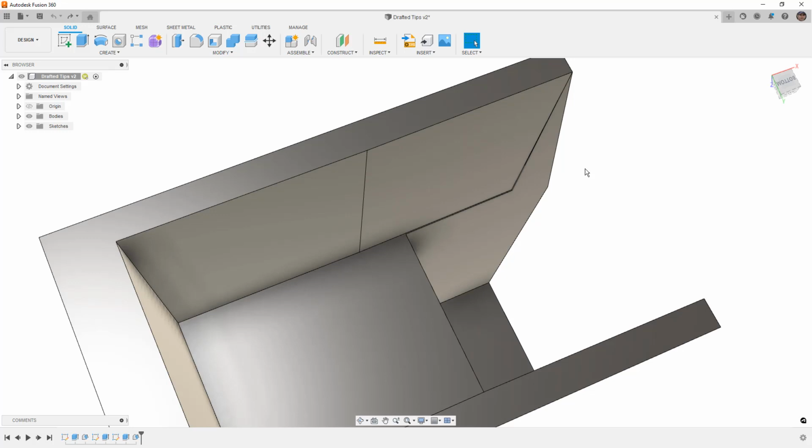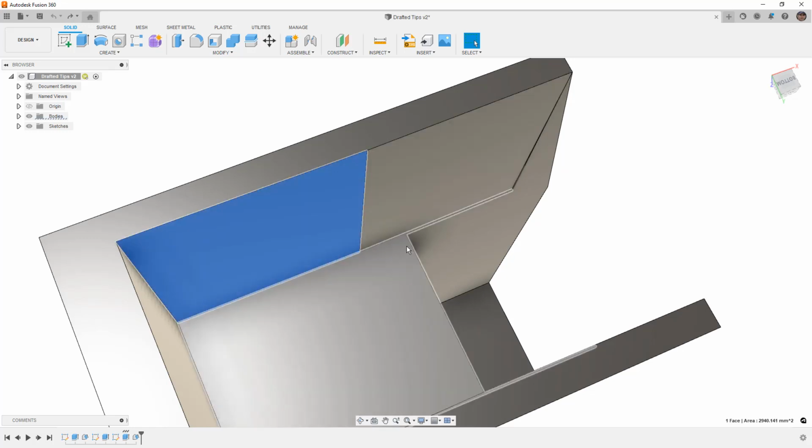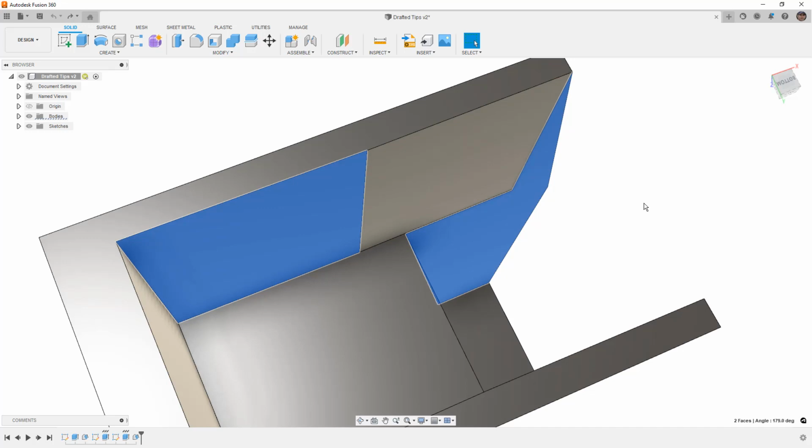tool. Now, delete is extremely handy in a lot of direct modeling cases, and Fusion is actually pretty powerful at patching surrounding geometry, but we have to be really careful with our selection. So for example, we want to fix this face. We want this face here and this face here to be nice and smooth, to have the same draft on it. We don't want to send this file out to manufacture and have somebody send it right back.